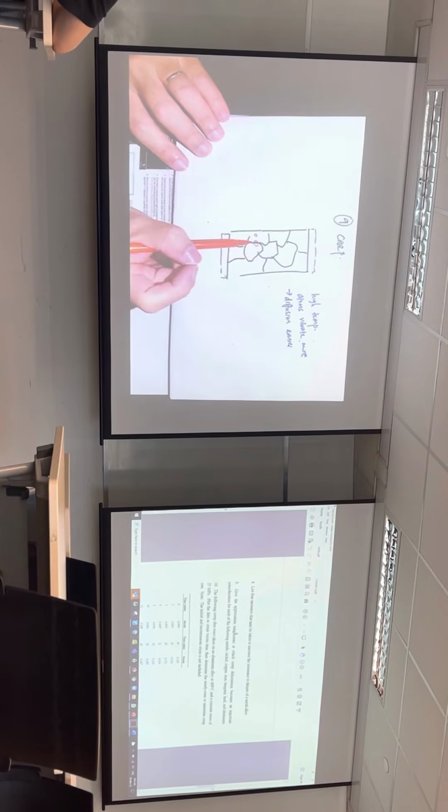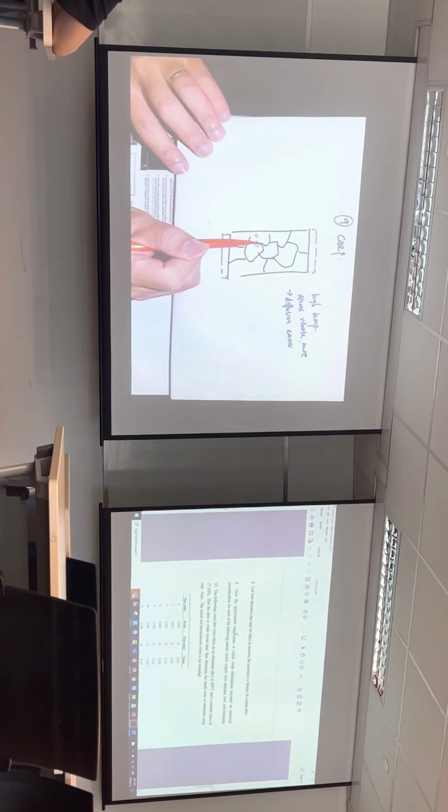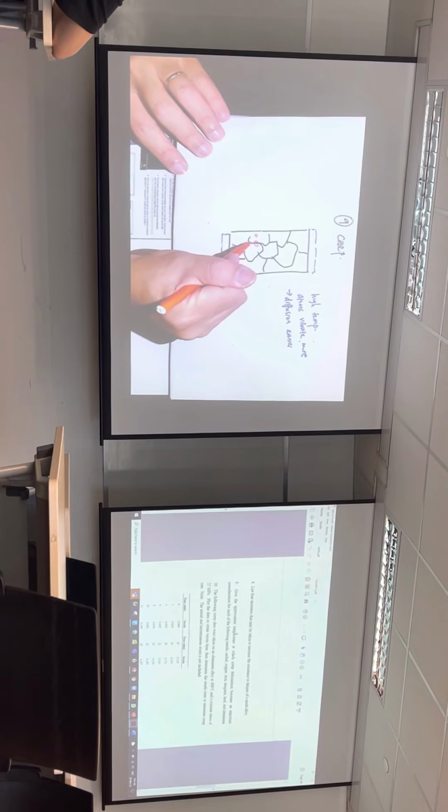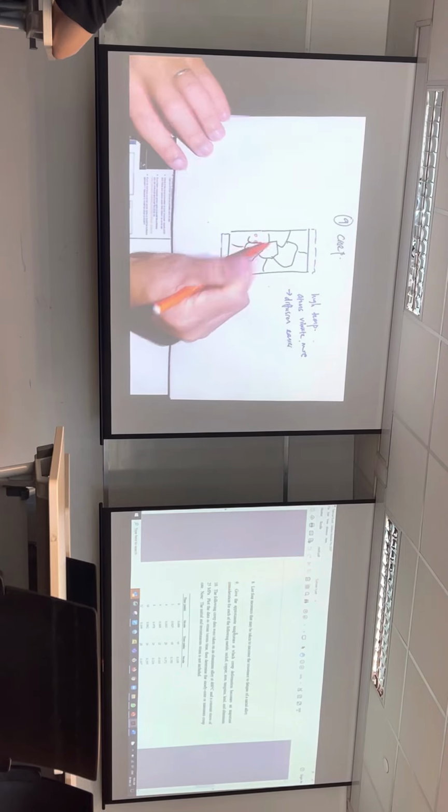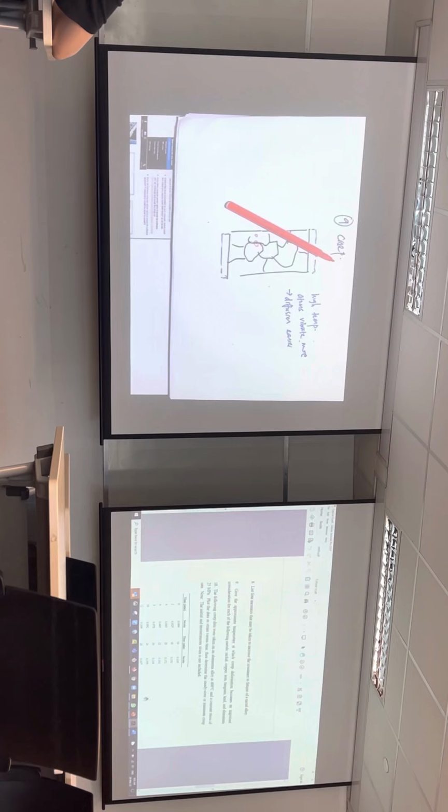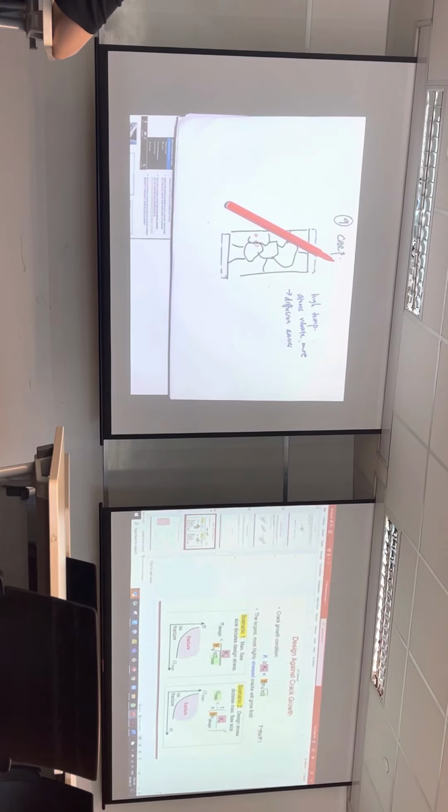The one at the grain boundary is not as highly coordinated compared to the grain, which means it has fewer neighbors. If I want to move, I only need to break fewer bonds. So for these reasons, all the atoms at the grain boundary are the preferred ones to move. When they move, they leave behind dangling bonds that need someone to stand by.